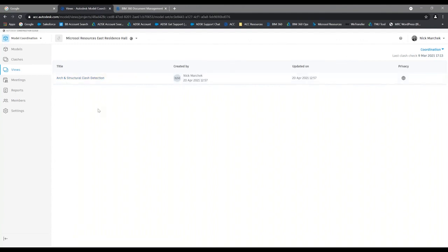So ultimately the answer is, at that point, it's a matter of workflow as to who you want to be running the clash detection. If they have full permission and have a license of BIM Collaborate or BIM Collaborate Pro, they can access the models. They can run model clash detection. They can share anything with you as the architect, or me as the architect in this example. And so both parties can basically use the clash detection functionality at that point. You just have to have the license.